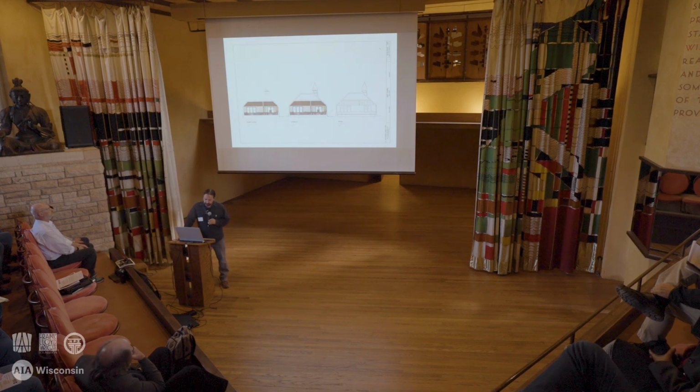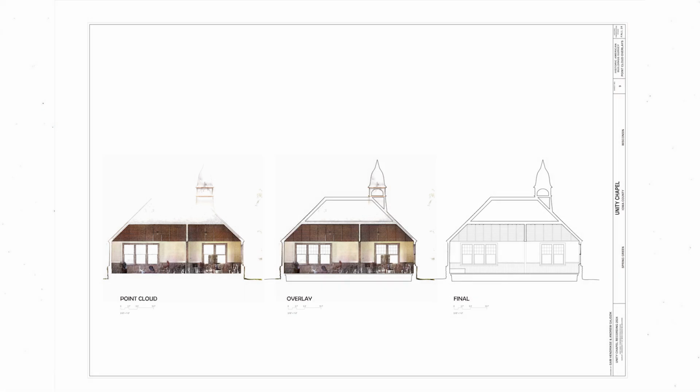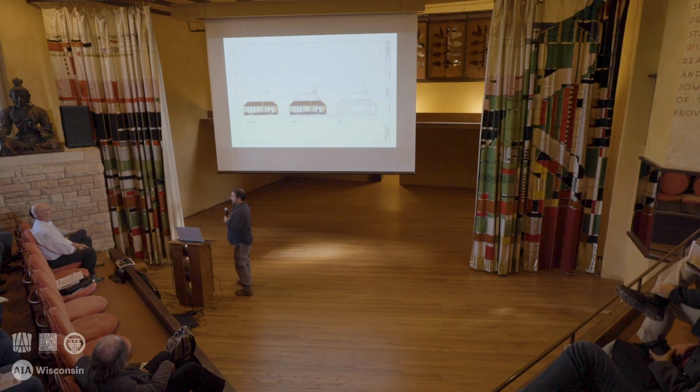But, you know, even just with the point cloud alone, it's a great tool to see what you can do with it, what you need to do with it, what are the issues. Sometimes with these buildings, we notice right away that a wall can be out quite a bit. You can see it with the naked eye, but once you get the scan data, now you've got something that you can quantify, and you can relay all that information to your engineers.